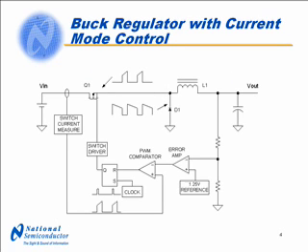Shown on this slide is the same basic buck regulator power stage with the addition of the control circuitry. Control is accomplished through pulse width modulation of Q1. This particular control circuit is referred to as current mode control. The main characteristic of current mode control is that the modulating ramp used by the PWM comparator is a signal derived from the buck switch current. When the buck switch is turned on, the current rises with the same profile as the inductor current.